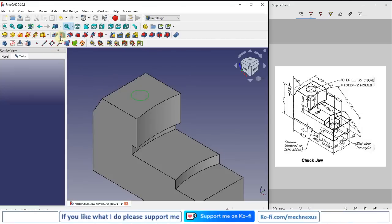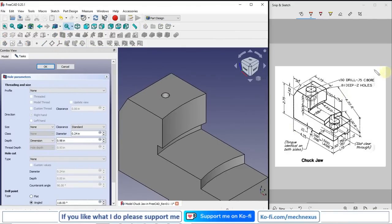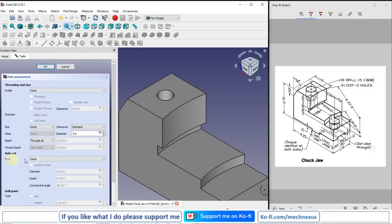So I will go for the hole, and here 0.5 is a through drill, so I will give here 0.5 and I will say through all, and here in hole type I will select counter bore, and counter bore diameter is 0.75 with a depth of 0.81. So I will give 0.81. I will say okay.